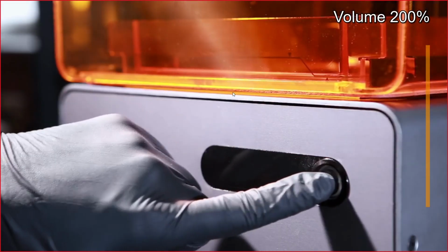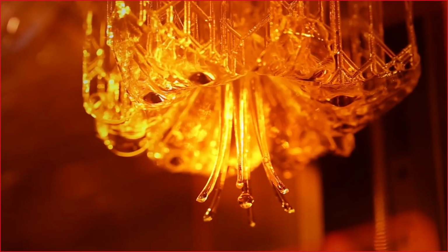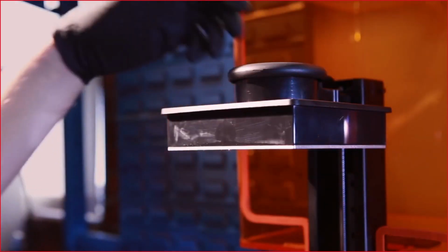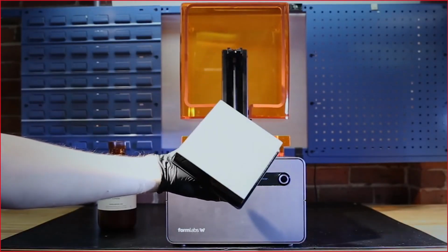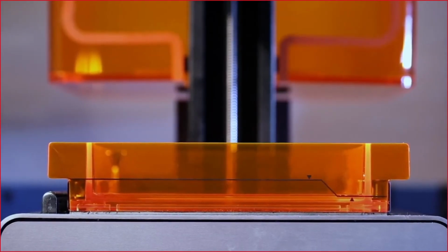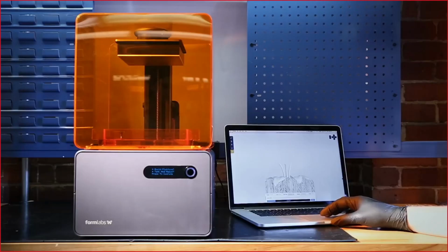The Form 1 Plus is a stereolithography 3D printer Today, we're going to take a look at how it works and put it to the test against parts from an extrusion-based machine. Let's start by taking a closer look at the printer. When we open up the light-blocking cover, we can see a build platform inside. This metal plate is where the parts are made. Underneath the build platform is a resin tank. This clear window gives the ultraviolet laser a path to cure the resin.